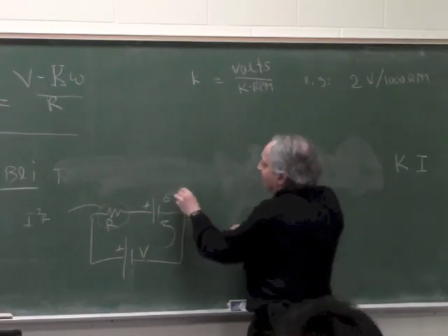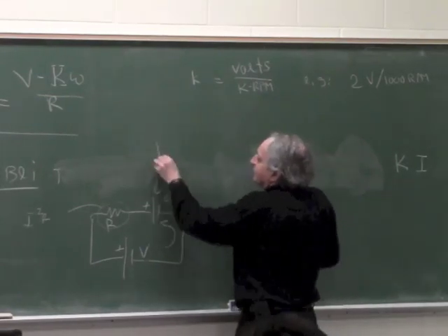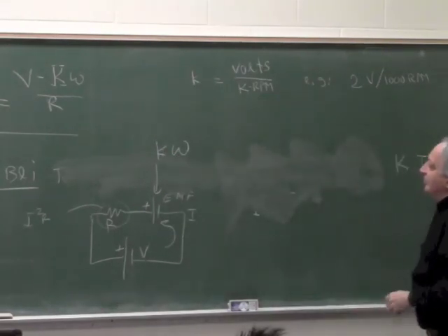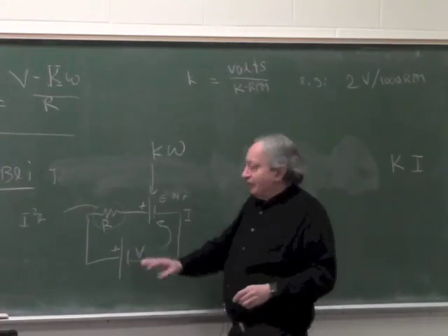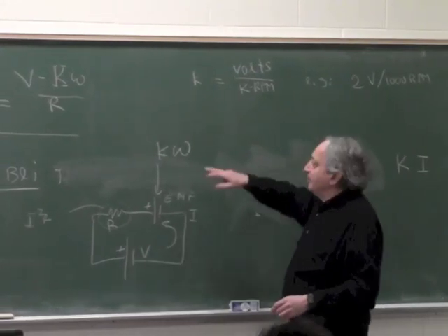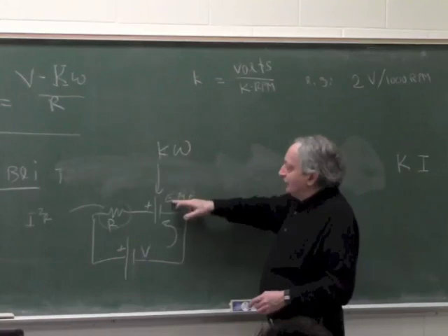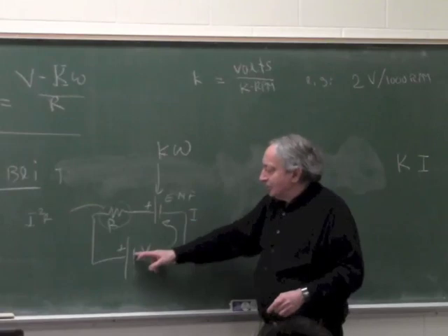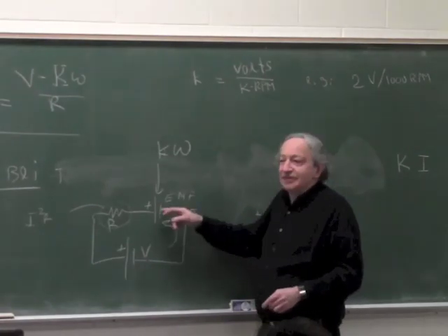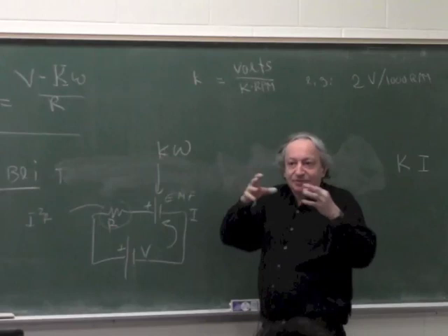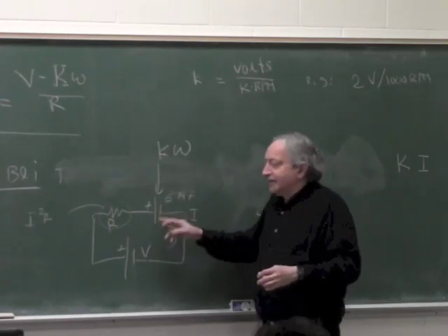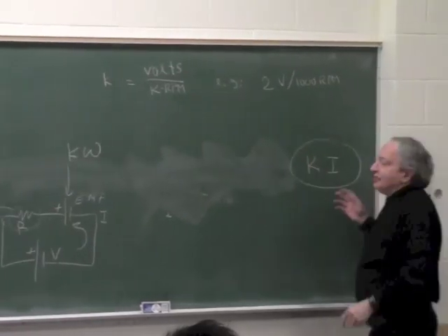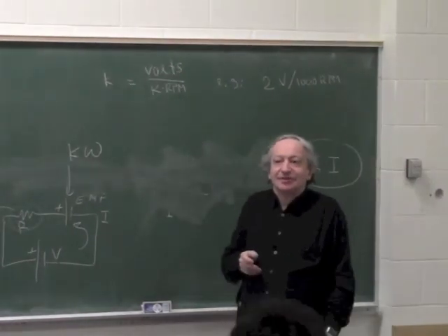So the back EMF, as we proved before, is K times omega. Okay? So if you had no resistance, for every voltage, the motor will spin at omega until this voltage equals this voltage. Because if there's no resistance and the voltages are not equal, the current will be infinite. If you take two batteries together with no resistance, the current is infinite. If the current is infinite, it will generate infinite torque, and the infinite torque will immediately correct the speed.